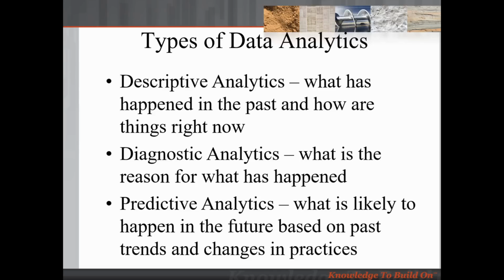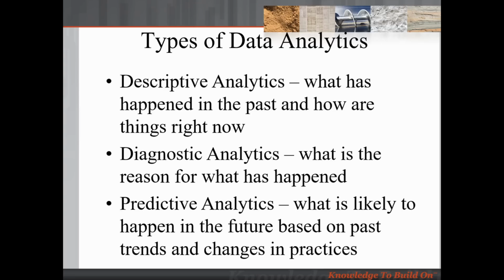So when we talk about data analytics, there are three main types. First, you have descriptive analytics. What's happened? What's a typical pile length for a given capacity at a given location? That's merely descriptive. Diagnostics would be identifying where piling were either much longer or shorter than planned and determining a root cause for such a situation. And then finally, you have predictive analytics. That is to take a given set of conditions, a certain site, certain pile size and capacity requirement, and be able to predict the likely outcome for the installation of that pile.